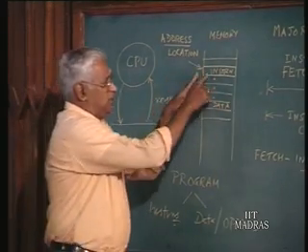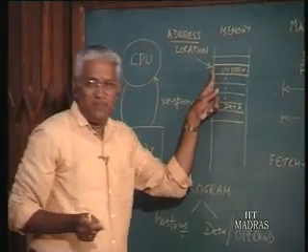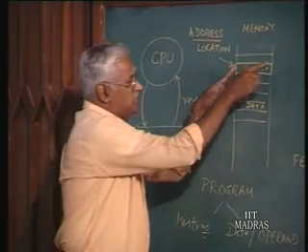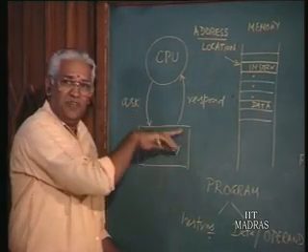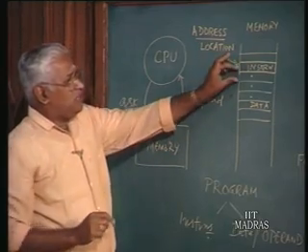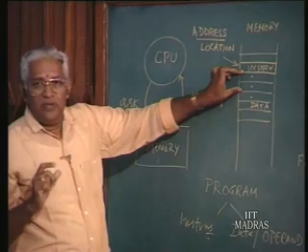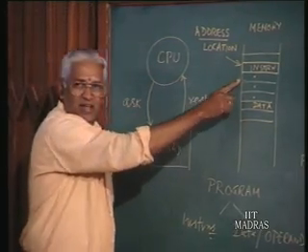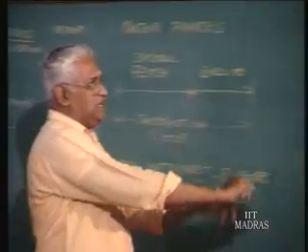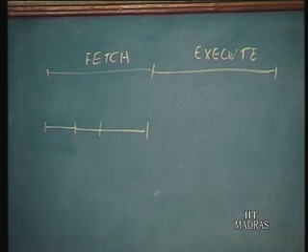It is possible that the instruction is occupying more than one location, in which case, if this is the unit of data that the memory can put on the bus or the CPU is capable of getting, then assuming the instruction is put in 3 locations, the CPU will have to place this address and then this address and then this address. So, that is what I have indicated here. I am just assuming the instruction is fetched in 3 phases. Okay. Now, every time what does it do?